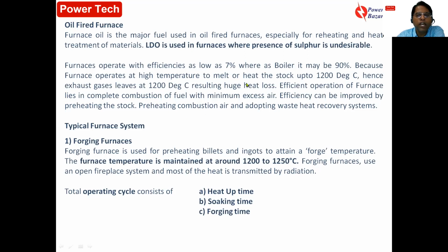Now if you can preheat the stock or combustion air, or employ waste heat recovery systems in the furnace, then furnace efficiency can be improved. Now let us understand typical furnace systems.